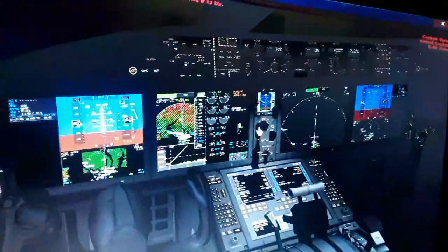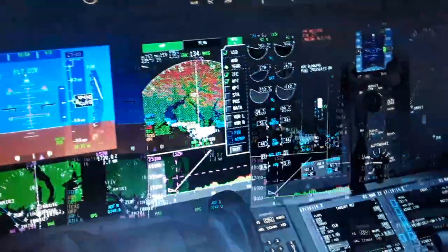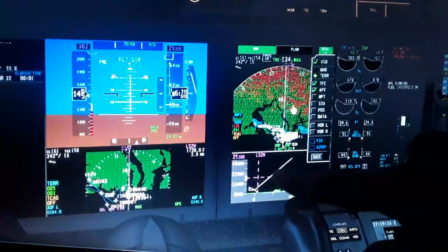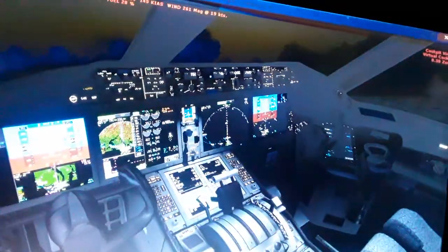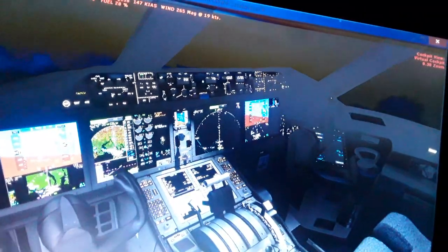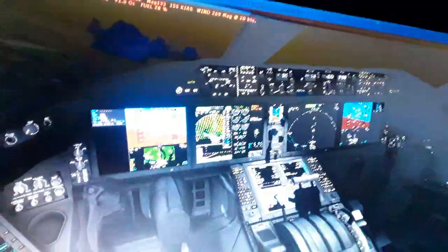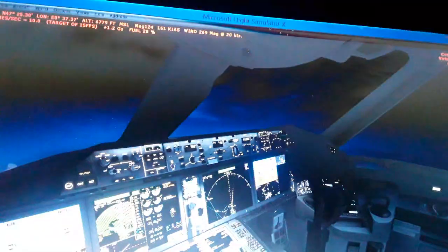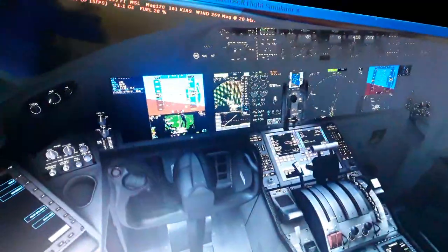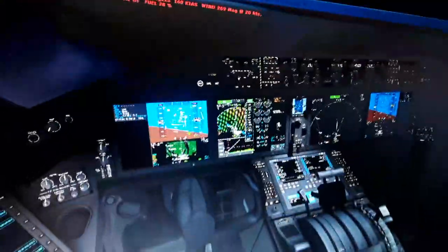So we're gonna use more airspeed now for the climb. You can see also the initial climb, the path here where we need to climb to, and start making perhaps the turn now. So you can see we use this to control the aircraft, and the rudder pedals to make the turn.